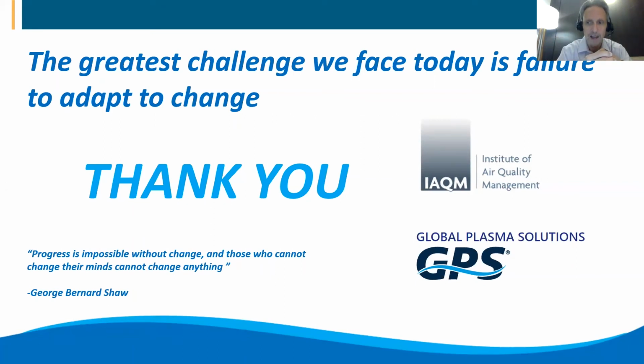So, follow the guidance, follow the UL Underwriters Laboratory website, go in and validate any electronic air cleaning product that you are considering applying to the space. All you need to do is jump on their website, go into Spot UL, type in the manufacturer's name, and in front of you should appear pictures and model numbers of the products that they have sent to UL to have tested and validated. If nothing shows up, they're not validated. If their product array shows up, they most certainly are. And I highly recommend you do that. Any electronic air cleaning product whatsoever, anything. Does that answer it? That's perfect.